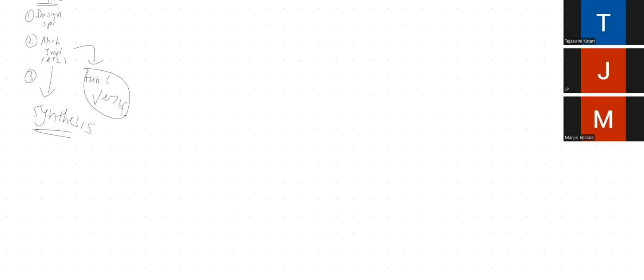So, sir, as you mentioned, if we do the synthesis step, then we'll get the power, area, and performance. It will give you the accurate gate level netlist, and it is also technology dependent, right? So that's the reason we are using the synthesis step.